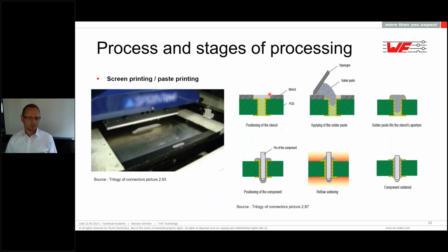On the second way, you can also add more to get more solder paste inside the via, yeah, to have the right fill. Like here, we can see this looks pretty perfect. Then the pin is inserted inside. There's solder paste all around, it goes through the oven, and we see a perfect result here. That's how it should be, of course.